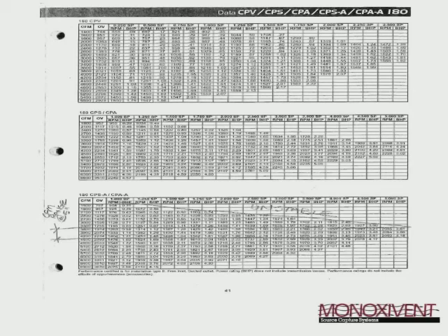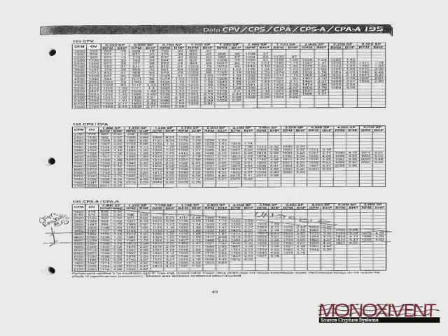So in this example, this is a BI 180. It's an 18-inch wheel, and we're talking about a 5-inch static pressure. In this particular case, at 5 inches, the range is 4,200 to 3,600 CFM. That's basically a 600 CFM difference. A VFD would not be a practical addition in this application, or this fan would not work for a VFD system. Here's another bad example as well. This is a BI 195, a 19.5-inch wheel. At 5 inches of static, we're at 4,950 to 4,250, so basically a 700 CFM difference. Again, this would not be a good pick for that type of system.